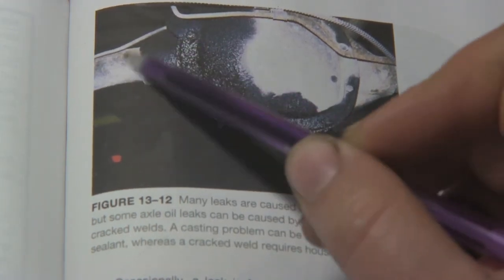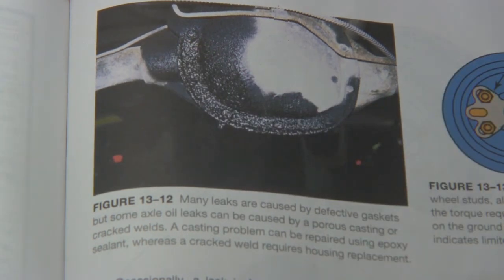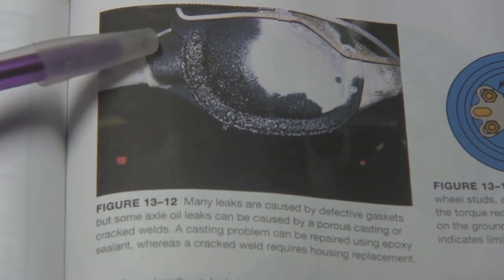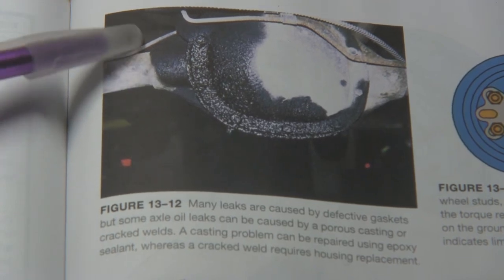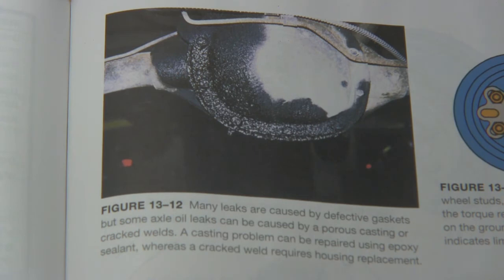There's not a whole lot you can do for that other than disassemble and seal it with some sort of RTV as you push the two halves back together. There's no O-ring in there. There's no seal from the factory. It's just a friction fit. But over time, with a really old axle assembly, you might end up with rust and pitting that water gets down in there, and oil starts to come back out. So don't overlook this little area right in here where the two axle halves, the axle tube, comes into the actual case itself.